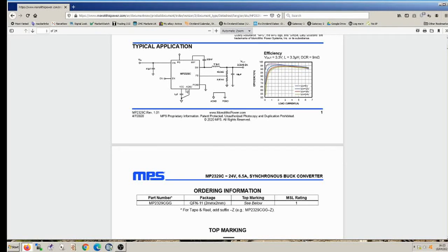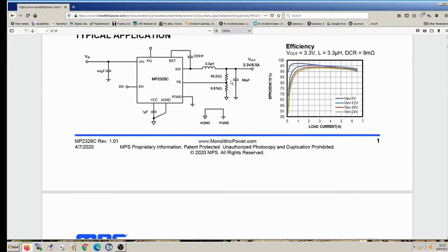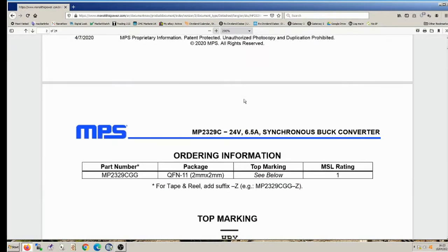Okay, so look, this is the regulator. We've got a voltage coming in. This will be the standby 5 volts, I'm guessing. And in this case, coming out is 3.3 volts. It goes on to show you there's a feedback and there's 2 resistors here. Let's make it a bit bigger so you can see, because I know this doesn't focus perfectly. So voltage in, output's 3.3 volts, but ours is 1.8, and there's 2 resistors here. And those resistors, depending on the ratio of these 2, will actually give the output voltage. They'll control it to go into the feedback.